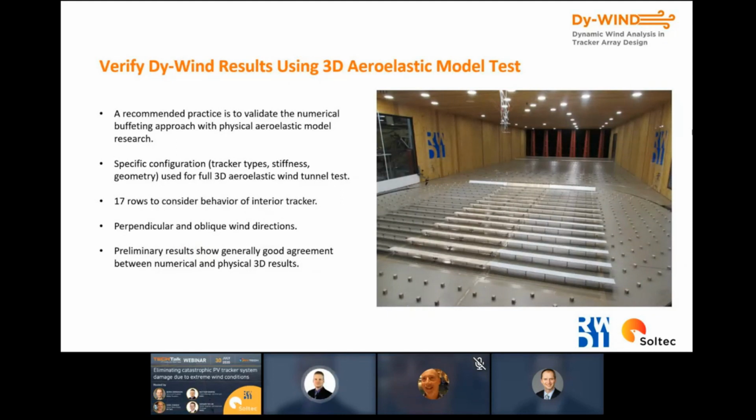And if we think back to the animation that Bernd showed from the buffeting analysis of the 7 rows, with each row moving in reaction to the wind, that represents effectively a numerical representation of a 3D aeroelastic type model, and we can do that in the wind tunnel.